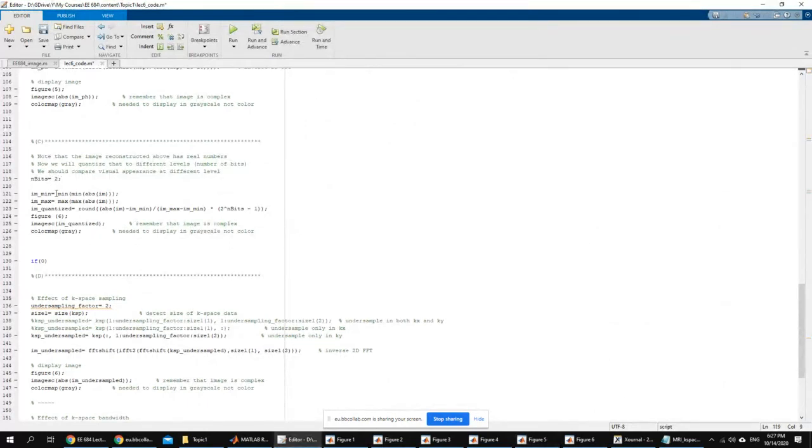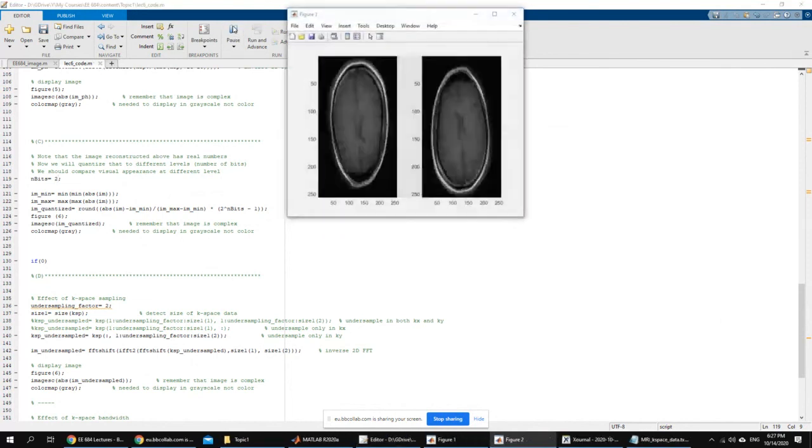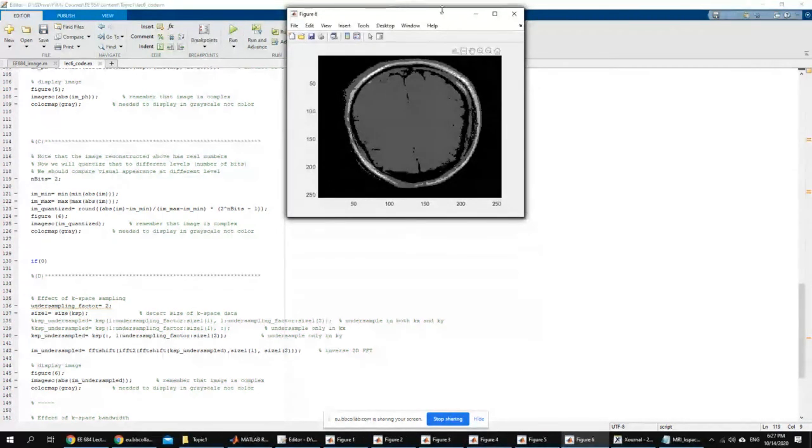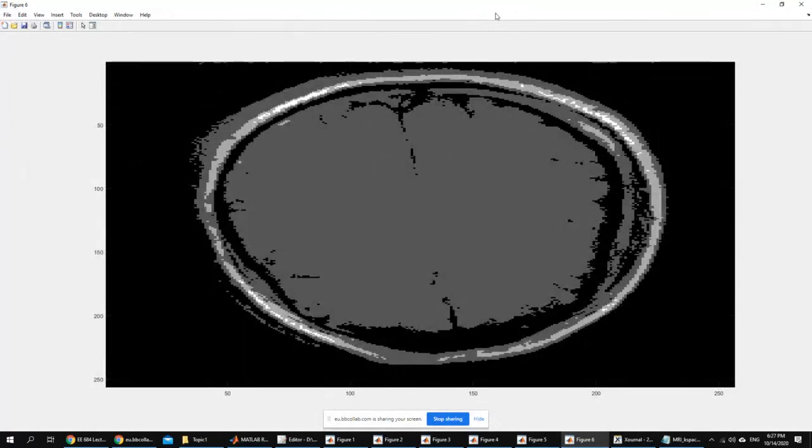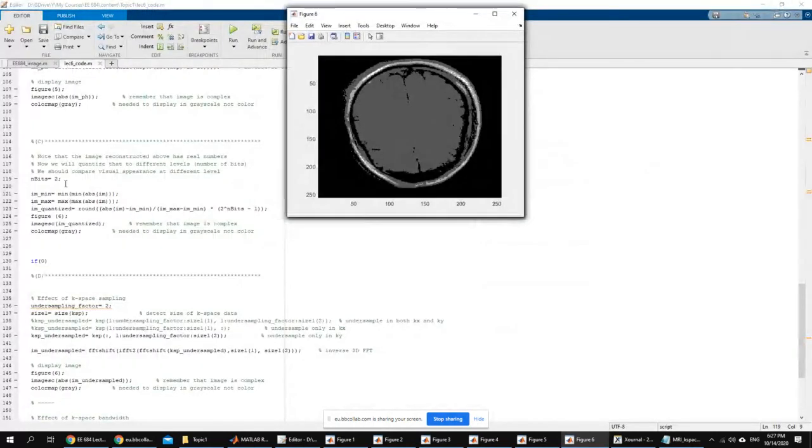Okay, let's start with something that looks bad first, because sometimes it's difficult to know the quality. Let's just put number of bits equal to 2. How about that? This is quantization. Each one of the points in the image is quantized to 2 bits. So you have only 4 colors. Is that okay? It doesn't look okay, right? So we need more quantization than that.